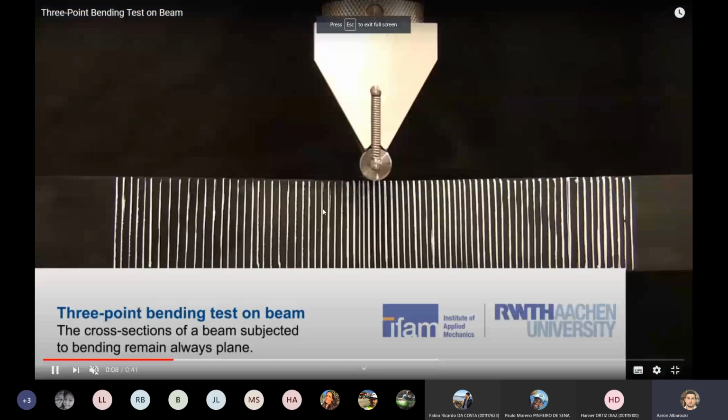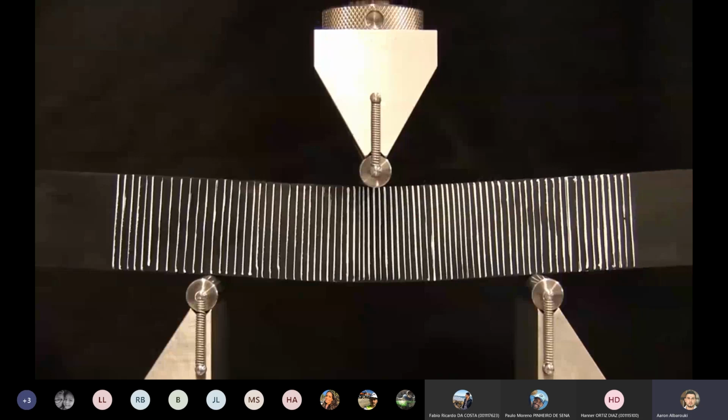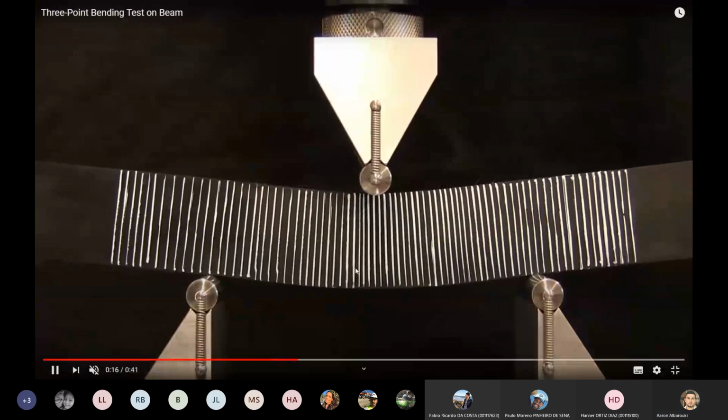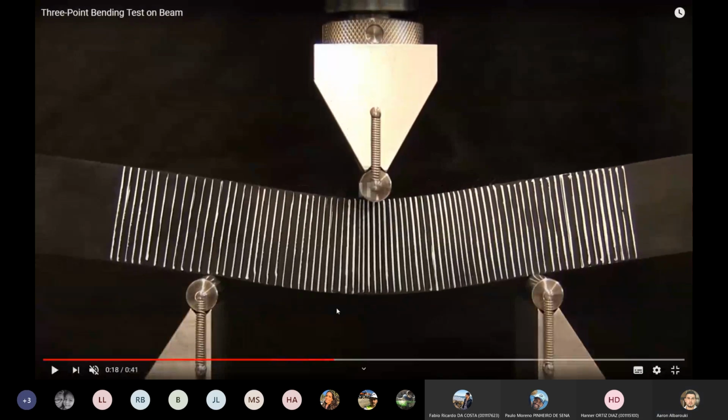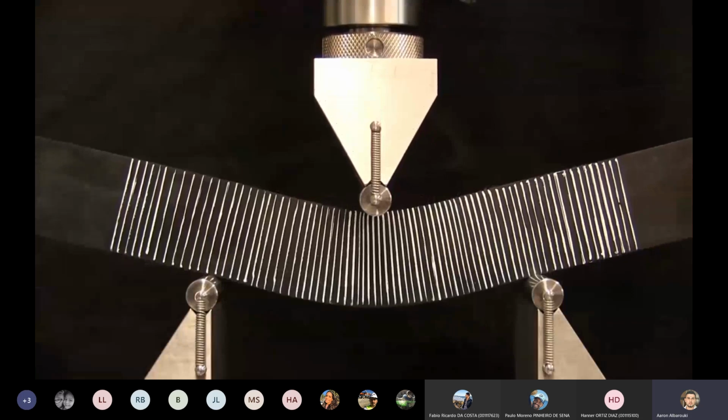The combined stress containing, if you look at this shape here, when I'm bending a member, look at these lines. This is pure bending. Look at these lines, they're coming very close to each other here. They're separated at the bottom. That means this is combining two different stresses. These are being compressed and this side here being under tension. That's why we call this type of stress a combined stress between the compression and tension together. Okay? That's what we call a flexural or bending stress.